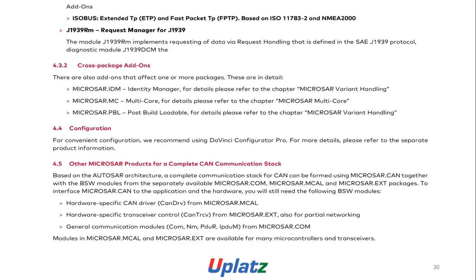Other MICROSAR products for a complete CAN communication based on the AUTOSAR architecture. A complete communication stack for CAN can be formed using MICROSAR CAN. For the PSW modules, MICROSAR COM, MICROSAR MCAL and MICROSAR EXE packages are separately available to interface MICROSAR CAN to the application hardware.